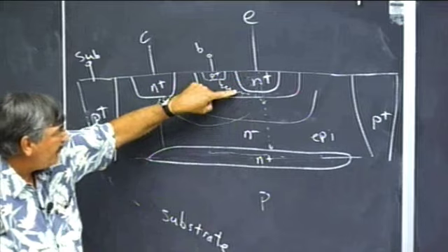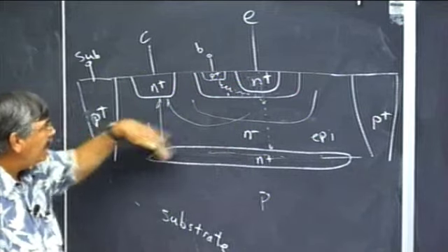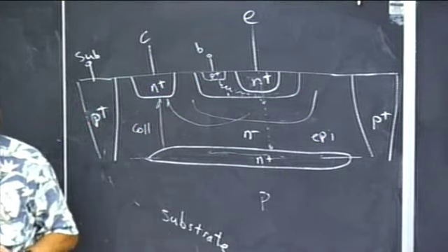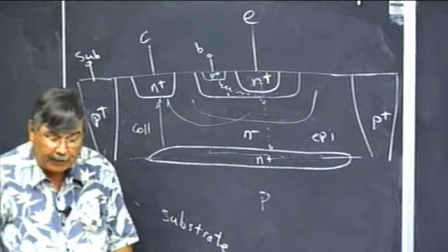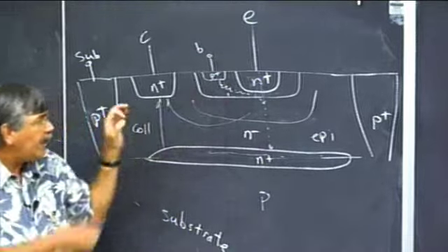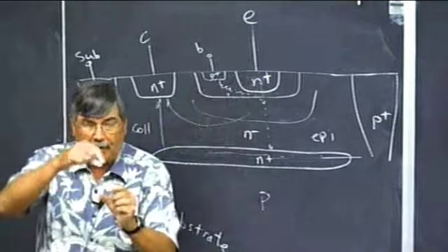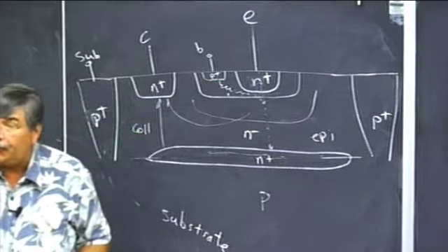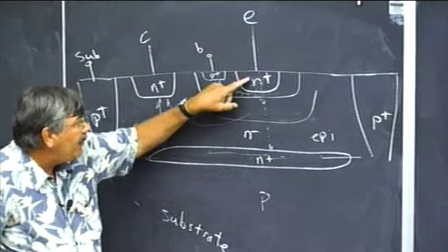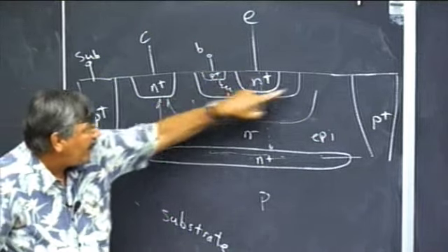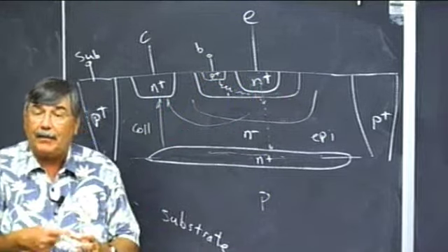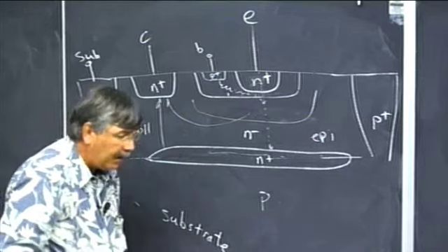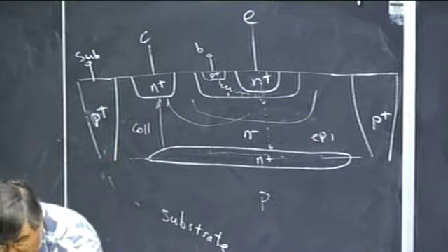Heaviest doping, moderate doping, light doping, trying to get our contact regions in as close as we can with as little resistance as possible. All right, a number of big problems here. The real problem is photolithography is still pretty good, but the ability to align a mask to an existing layer is not so easy. It would be nice if we didn't have to make sure this was fitted inside this region. You have to make everything big so that you don't accidentally miss. There are tricks that you can do called self-aligned processing that allow for better performance.